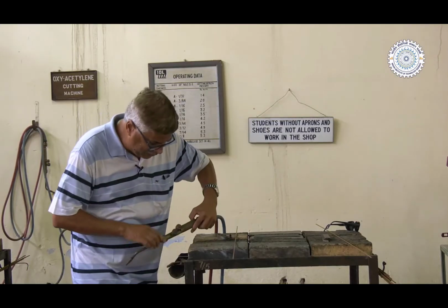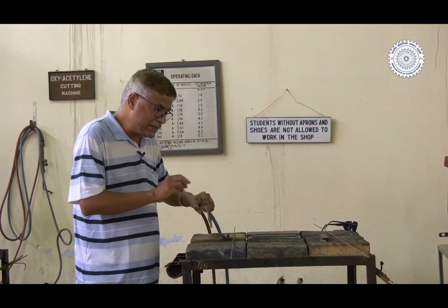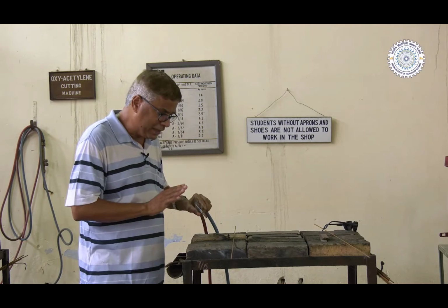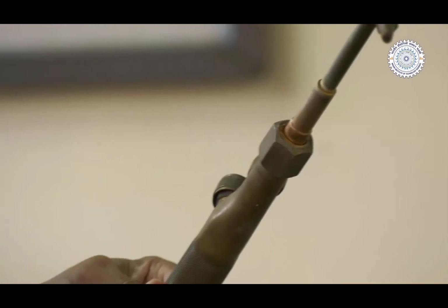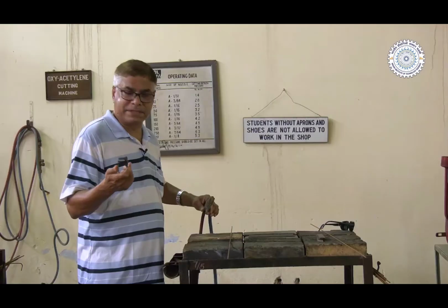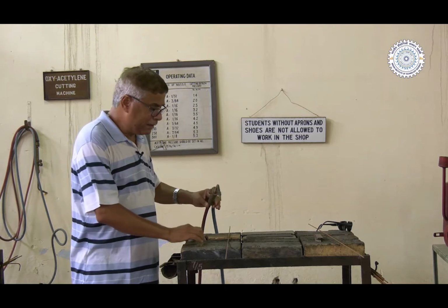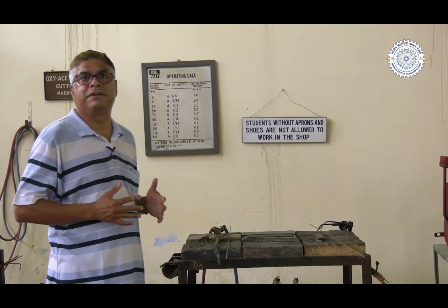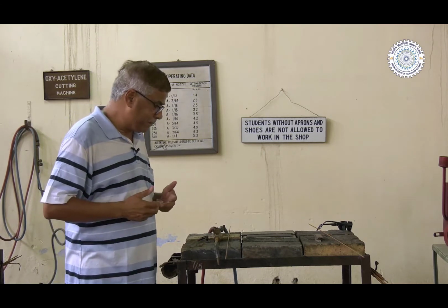You can see here one is coded with blue and another one with red. These knobs are used to adjust the supply of oxygen as well as the fuel gas, and that mixture of oxygen and fuel gas will come out through this nozzle, and using this lighting system, it gives the spark. So, the fuel gas mixture is burned, and through the adjustment of these knobs, by changing the proportion of oxygen and acetylene, different types of flames are produced.